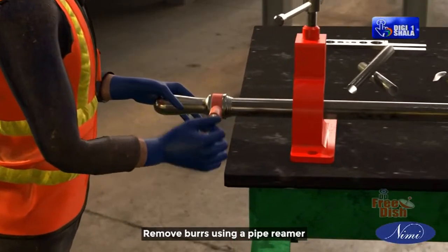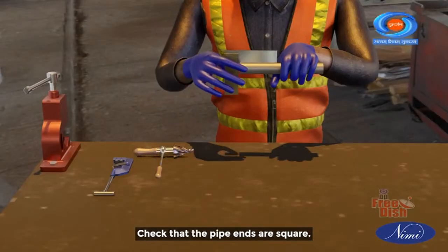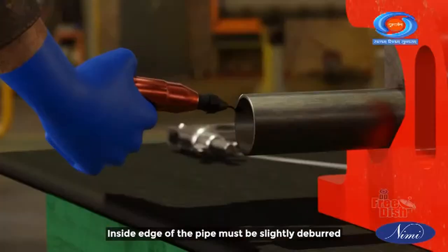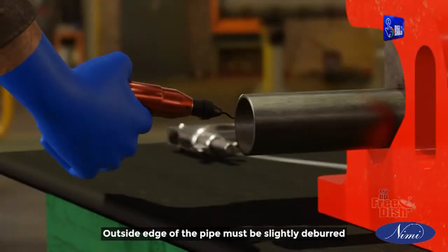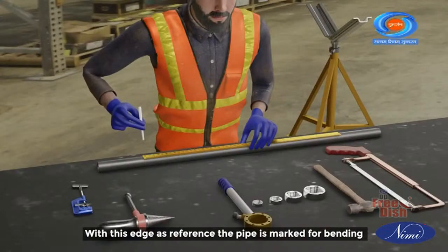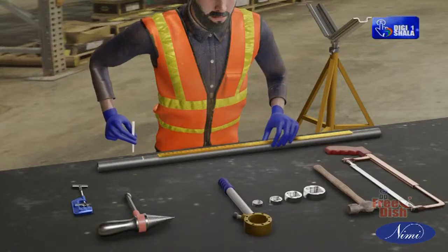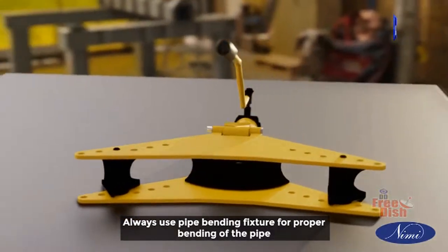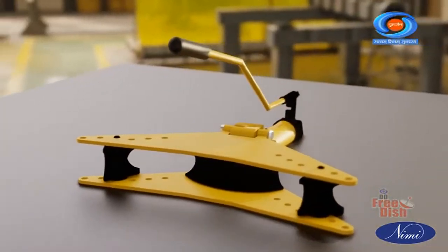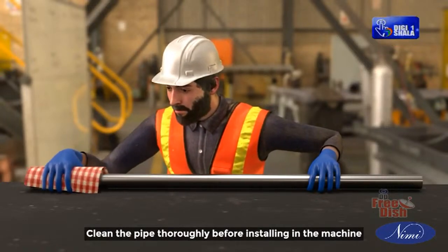Remove burrs using a pipe reamer. Check that the pipe ends are square. Inside edge of the pipe must be slightly deburred. Outside edge of the pipe must be slightly deburred. With this edge as reference, the pipe is marked for bending. Always use a pipe bending fixture for proper bending of the pipe. Clean the pipe thoroughly before installing in the machine.